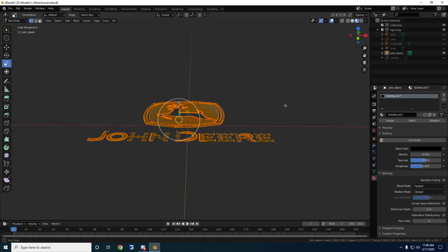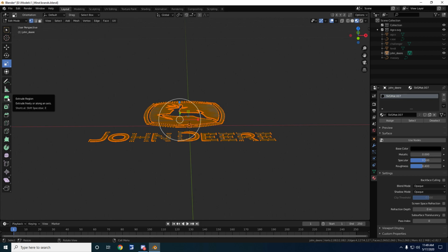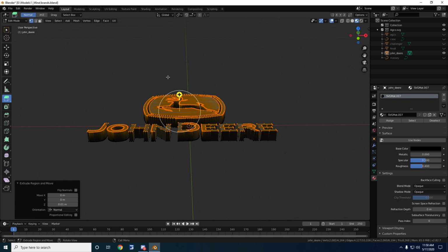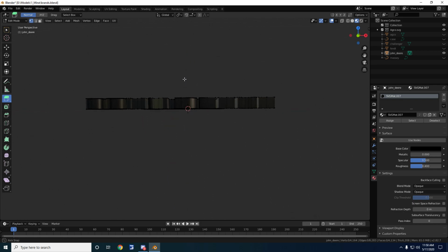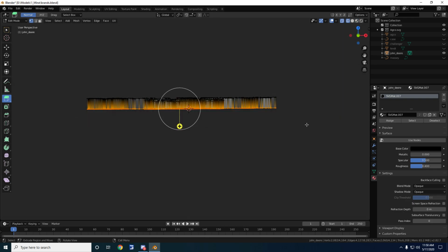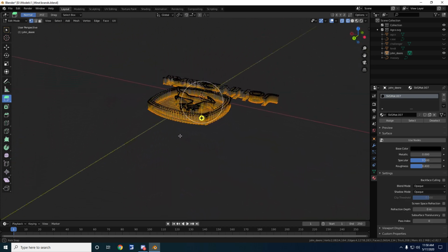So in order to clean that up, I'm going to select it in edit mode, click extrude, raise it up 0.01, sure. Then I'm going to hit delete the faces. Then I'm going to come down here, hit Z, wireframe, drag across the bottom, which should have grabbed all the bottom ones.